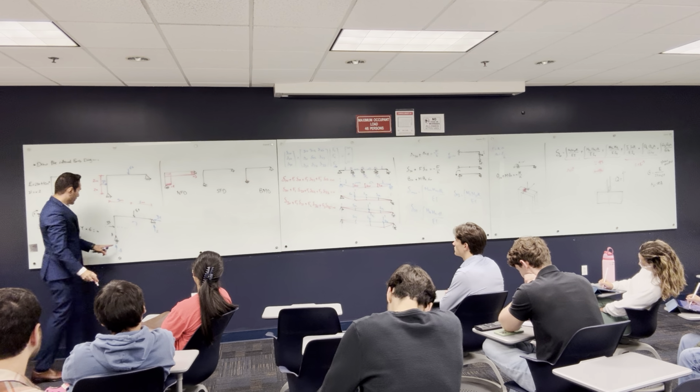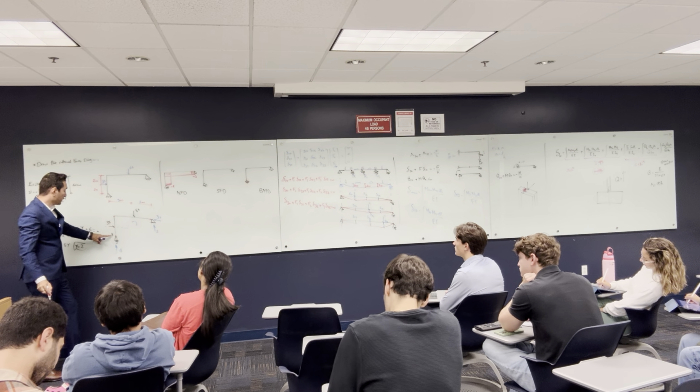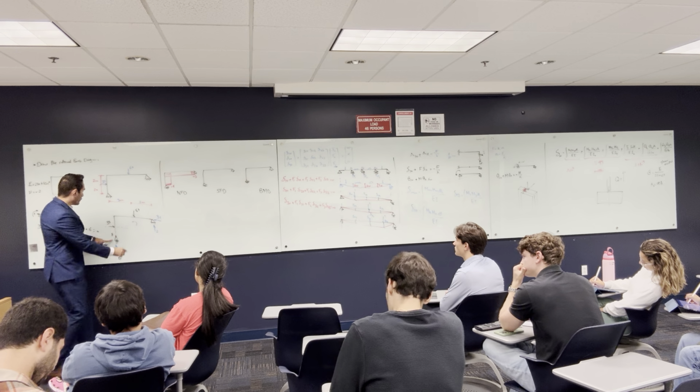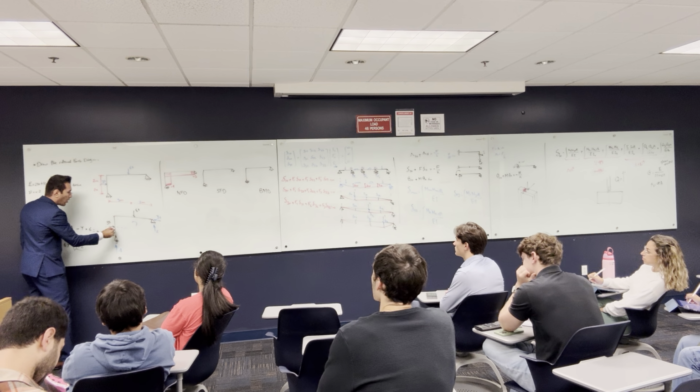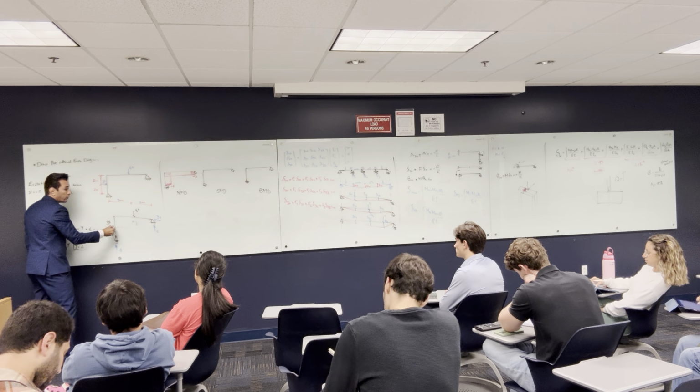How about the shear force? Is there any force that makes shear here? No, because there is no force here because this is roller. So the shear force is gonna be 0, 0, 0 until you come here. Before the 3, it's 0. After the 3, the shear force is not 0.